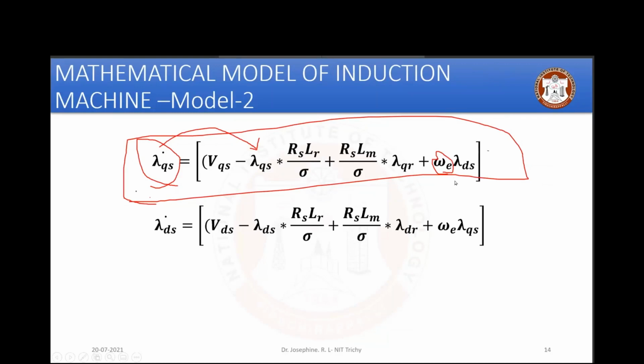Everyone, it is not mandatory that you have to go for vector control or direct control. Vector control means DQ reference. Direct control means alpha beta reference. They don't consider PLL and all, so it's hectic for them. So it's like one is ABB, one is Siemens. It's up to you how you choose. You don't need to follow both of them. You create your own controller, but make sure that you identify these elements properly. I'm talking with respect to hardware and software both. So there is one representation.